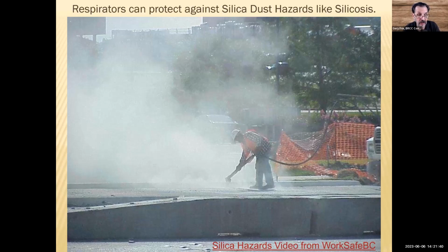It was already pretty strict for general industry, but it's become strict for construction too now. You have to vacuum the stuff instead of blowing the dust out of the cracks before you put in caulking. Running a concrete saw, you get rid of some of the dust because you have water on the blade to keep the blade cool, and it removes dust. But there's always dust to remove, and so that gets beyond that.